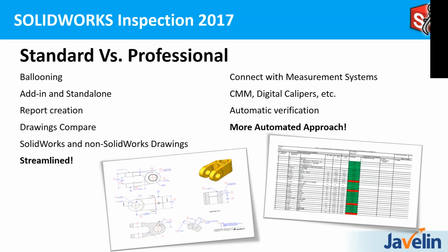So, standard versus professional. We've seen that both the standard and professional come with the add-in and the standalone, but we do have two different variations of the software. The standard can balloon, and it comes in the add-in and standalone. We have report creation, drawing compare, and we can work with SolidWorks and non-SolidWorks drawings, and it streamlines our operations. Now, the professional takes that a step further, where we can connect with measurement systems such as CMM, digital calipers, etc., and it does an automatic verification of our parts.